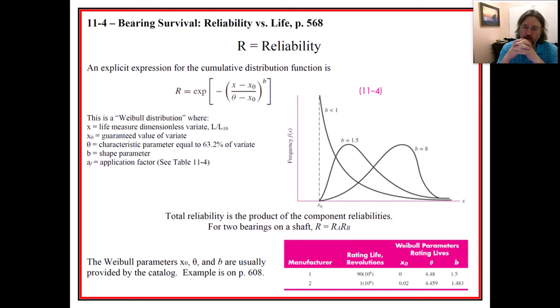bell. Well, for some industries and some applications, they found just over time that the bell shape didn't really accurately, or repeatably, I should probably say, give you the reliability distribution. It wasn't really a bell shape; there was a skew to it. So instead of having this Gaussian distribution, which is the bell shape, we can introduce something that we call a Weibull distribution. So this is a Weibull right here.